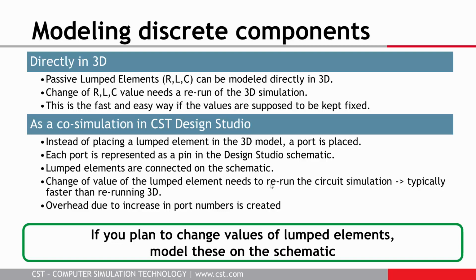Each of the ports will give you a pin in the Design Studio schematic. This is where you connect your excitation, your drivers, and any RLC models, and this is also where you define the signal which you want to use to excite the structure. There is of course a little bit of overhead because now the 3D simulation needs to simulate for 3 different ports. But if you want to change these values, this overhead is mostly not critical, and the coupled simulation will be much faster than putting everything directly into the 3D model.